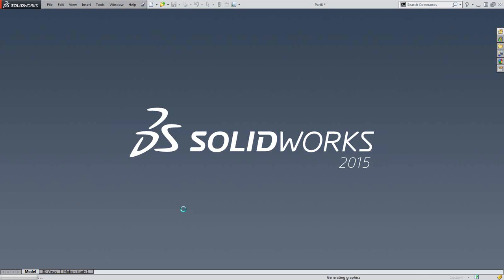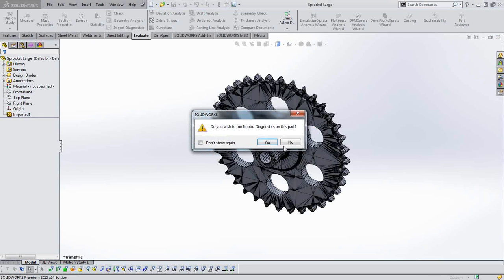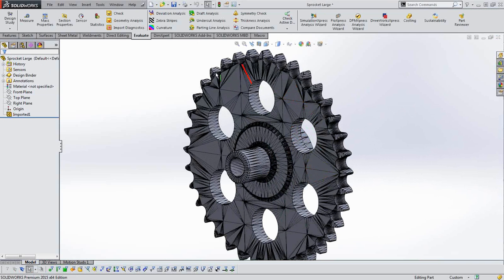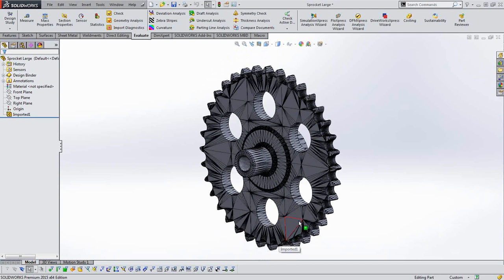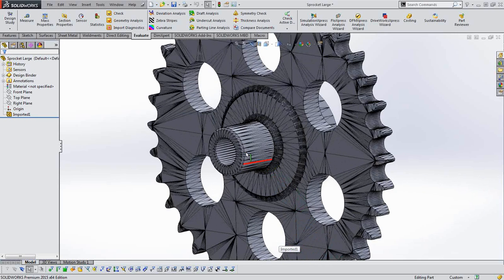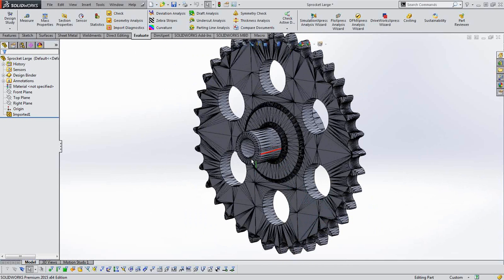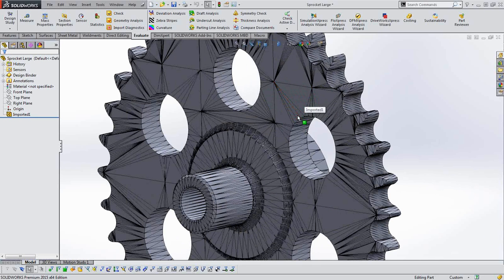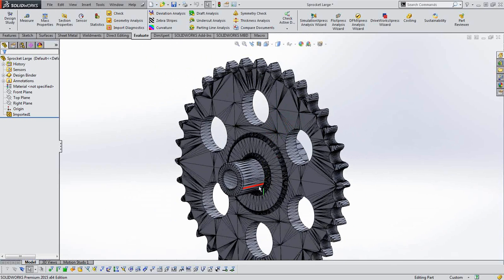So once we get this back up, running almost anything on this particular body would be very difficult. When you've got this many surfaces, trying to do any kind of direct editing, moving surfaces, changing things, is going to be extremely difficult, because you're going to have to find every surface and select it if you want to move just one.